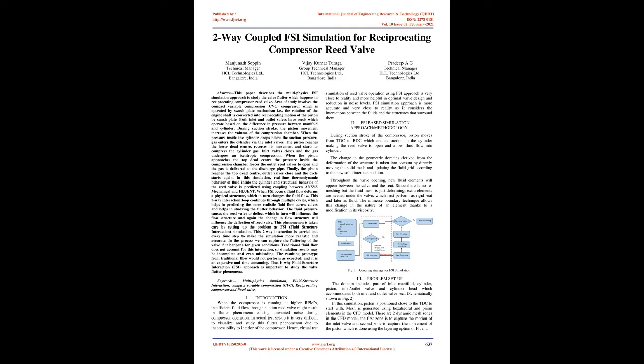Introduction. When the compressor is running at higher RPMs, insufficient fluid flow through suction reed valve might result in flutter phenomena causing unwanted noise during compressor operation. In actual test setup it is very difficult to visualize and study this flutter phenomenon due to inaccessibility to the interior of the compressor. Hence, virtual test simulation of reed valve operation using FSI approach is very close to reality and more helpful in optimal valve design and reduction in noise levels. FSI simulation approach is more accurate and very close to reality as it considers the interactions between the fluids and the structures that surround them.